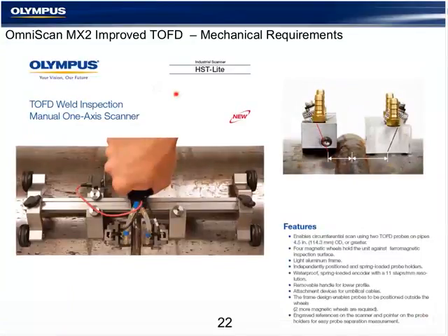Included in the download for this webinar is a new single scanner Olympus is marketing and including in their packages that has a lot of up-to-date useful features. A very hardy, durable, easy to manipulate, one-hand control. It's got a very nice encoder that doesn't slip when it's wet and in the couplant, easily adjustable magnetic wheels, and very, very useful.